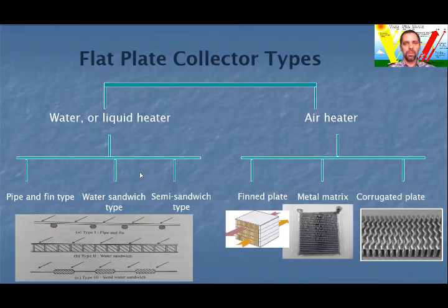For low temperature requirements, such as in warming swimming pools, the plastic full water sandwich panel may be the most appropriate choice. For domestic and industrial applications, higher temperatures are required and therefore higher efficiency, reliability, and long life are the main characteristics required. For such applications, pipe and fin type panel may be more suitable.